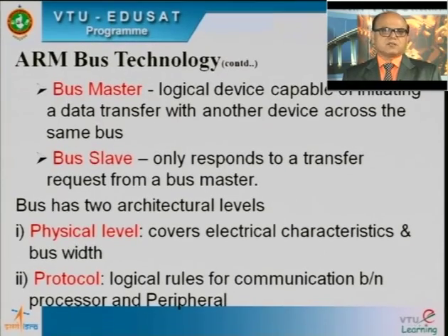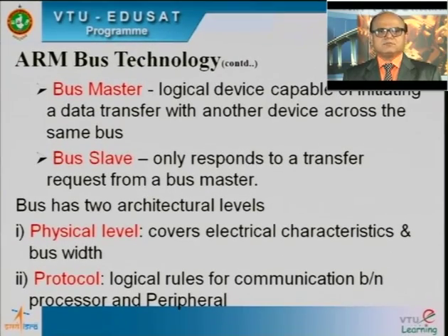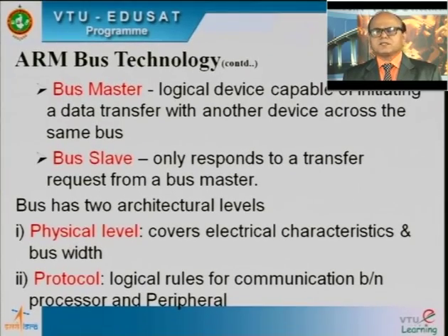The bus width is decided by the type of processor core. For example, many of the ARM cores are 32-bit processors. Naturally, the bus width will be fixed to 32 when the processor core is designed. Whereas similarly for 64-bit and others, the bus width will change.